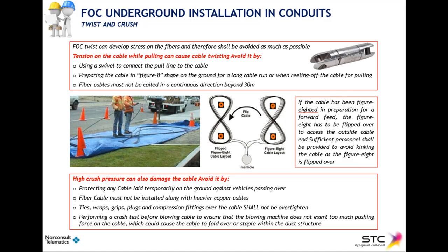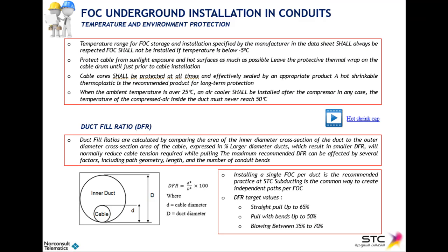Last, and specifically for blowing techniques, we have the crash test. We will see this in detail when we study the blowing installation techniques. Just keep in mind that a crash test is mandatory prior to any fiber blowing. Also remember that the figure 8 installation has to be flipped over if you are doing forward feeding to avoid cable kinking. Some words now about temperature and environment protection.